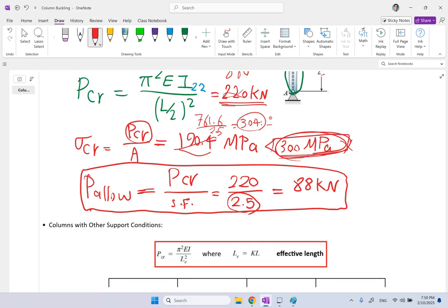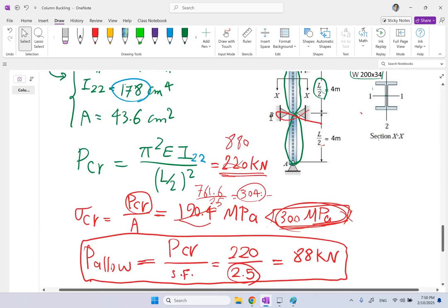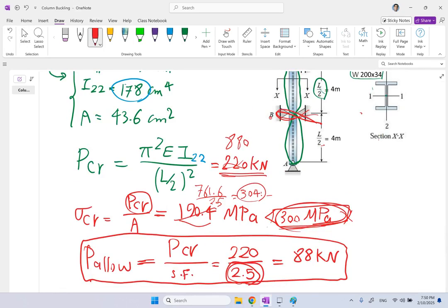Okay, and that means it is going to first surrender to compression, not to the buckling. So that's why we are supporting it here, to limit the failure to buckling, and by using a big safety factor, we make sure the buckling will never happen. So supporting the columns midway is an effective way to reduce the length that we use in the Euler formula.